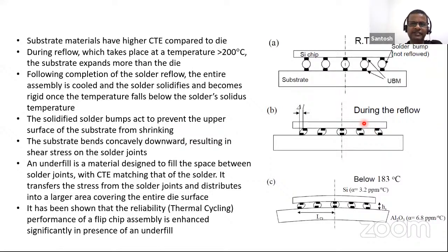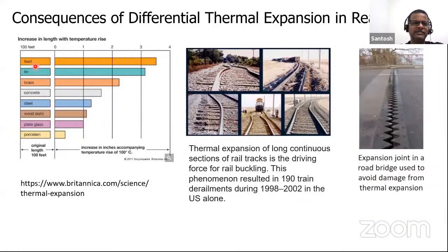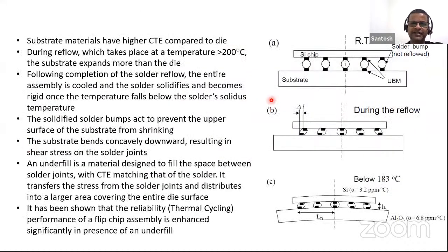But the expansion coefficient of silicon and the substrate are not the same. Like I showed here, you can see the rate of expansion of silicon and porcelain are not the same. If this is expanding at a faster rate, this is expanding at a slower rate. So similarly, the substrate here expands quite a bit compared to the silicon. But these guys are molten, so that's fine. So at some point after the reflow and bond formation has occurred, the assembly has to be cooled down.